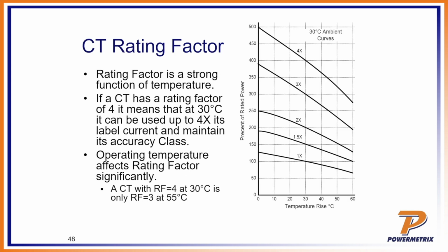But look at this chart for a minute. This is important, especially if you're in hotter places, like say you're in Arizona or southern Texas or down there in southern Florida, the places where it gets very, very hot. Or you're in a pad mount where you have all these CTs inside a box and there's nowhere for the heat to go. Look what happens to the rating factor. The rating factor is a strong function of temperature.